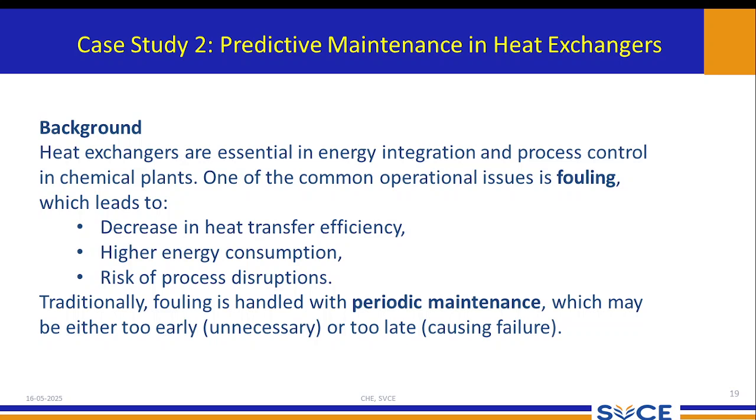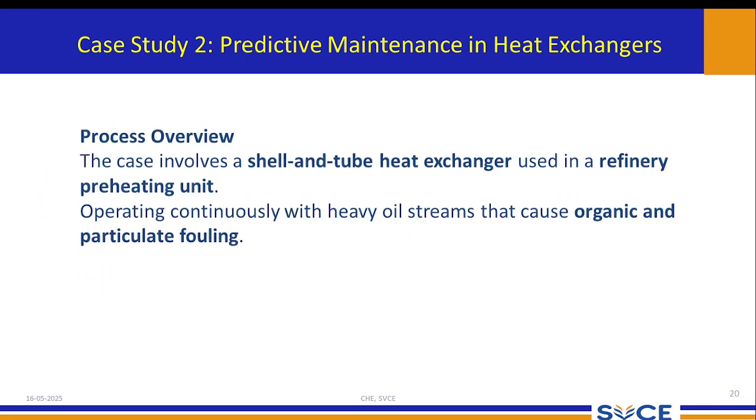So you should not clean things very frequently, because that increases the cost unnecessarily. If you do it in the early stages, it is more than required. Or if you do the periodic maintenance too late, obviously that will cause a failure of the process. The heat exchanger will not be effective.